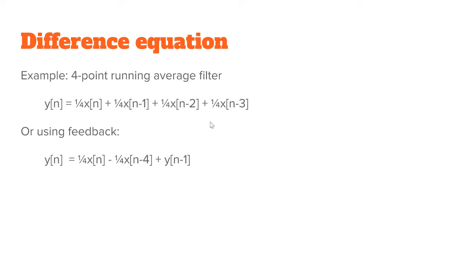But if you use the previous value of the output, you can subtract the oldest value and add the current value to the running sum.